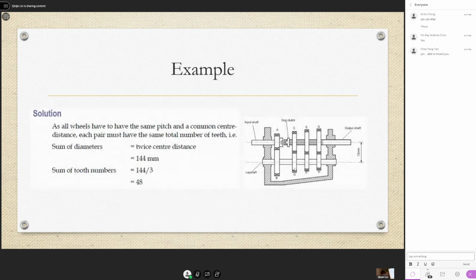They tell you down here it is 72. So from the center of the shaft here to the center of the other one is 72 mm. So if this 72 accounts for one part of the top gear and one part of the bottom gear, in total the diameter of the two gears must be 72 times 2, correct? It's like adding the diameters up together. So that's 144.